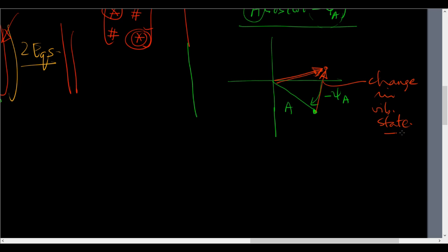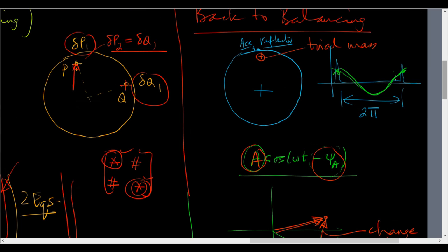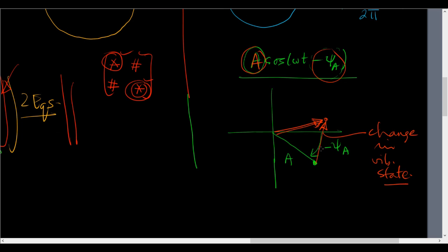I am showing it with phasors because every time I measure a vibration, I have an amplitude and I have a phase. What is the phase with respect to? With the spike, which is the same every time because it is the same reflector going round and round, some signal like that.